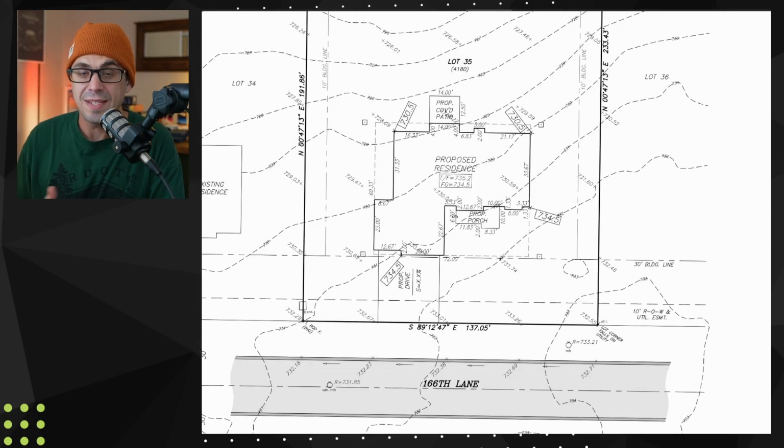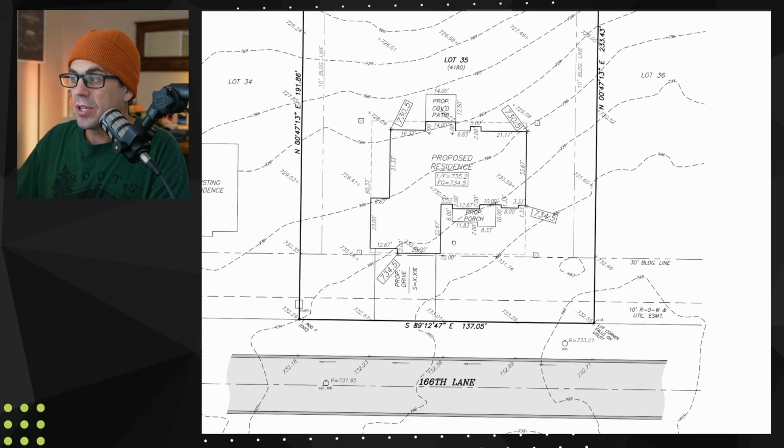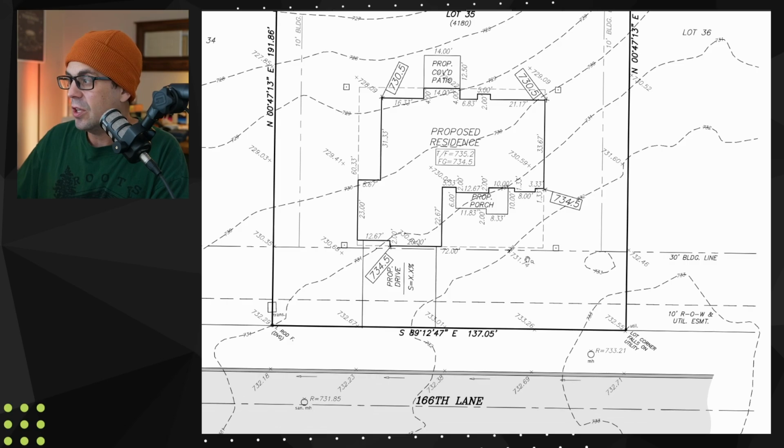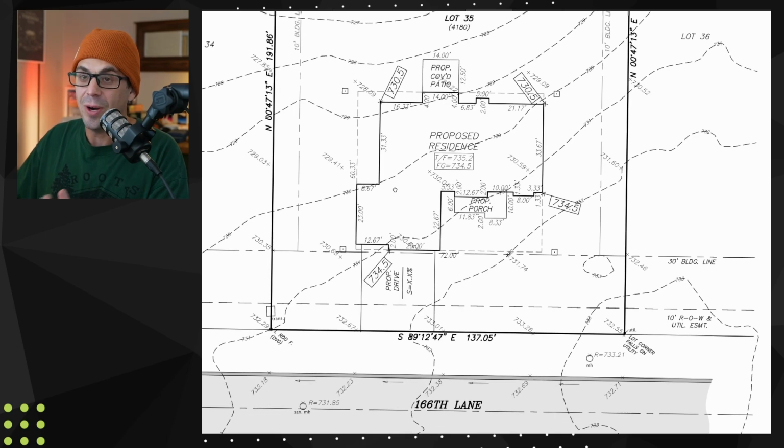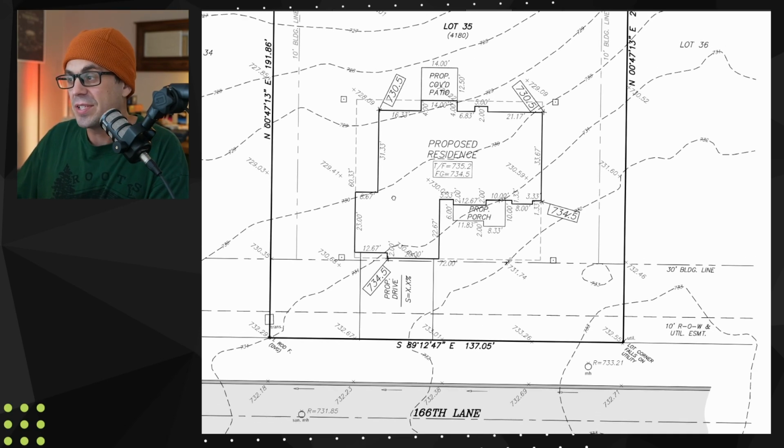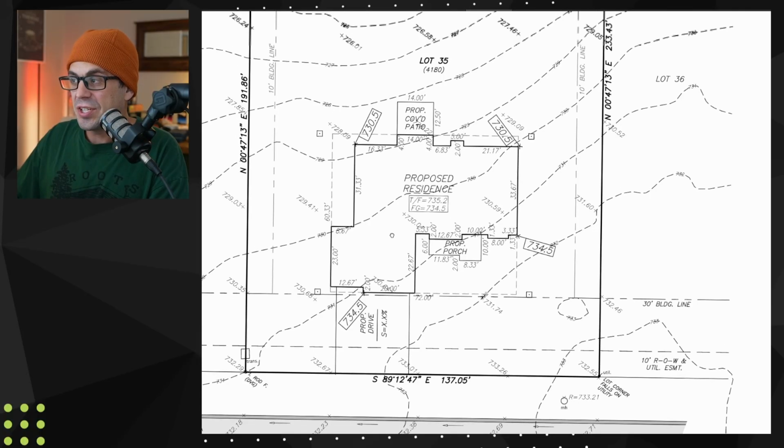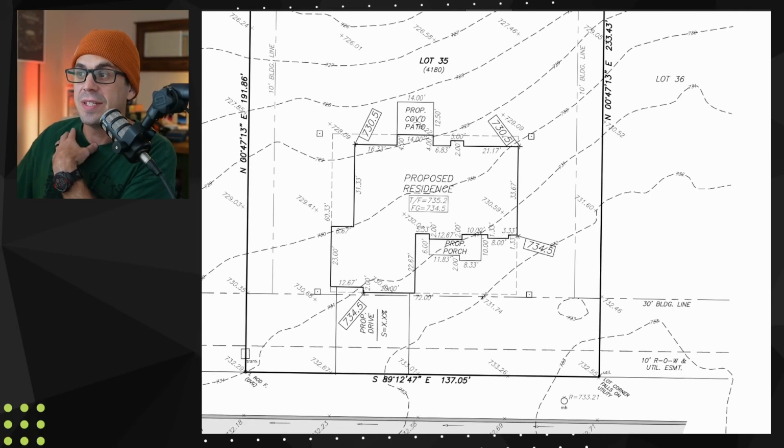Now we're going to put all that together and actually start to put together the permit pack that you'll need to submit to your city or county. This would be after the home is designed. You'll send the home footprint back to the surveyor and they'll place it on your parcel for you. They're also going to do some really important things like locate anything like a transformer, anything that's there already on your site, they will locate. And additionally, they're going to set the elevations for your home.